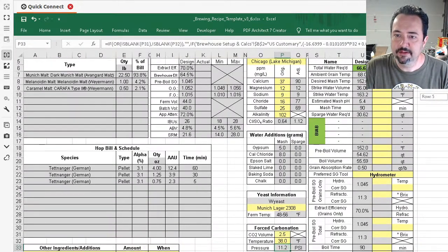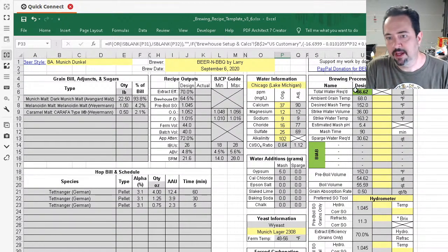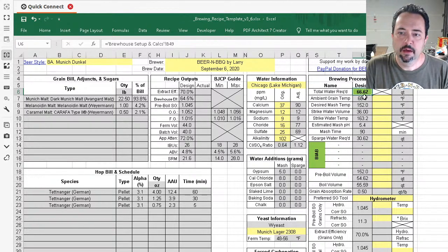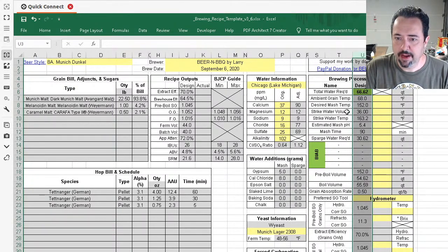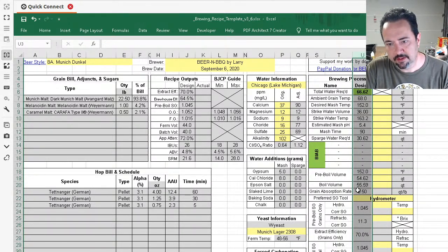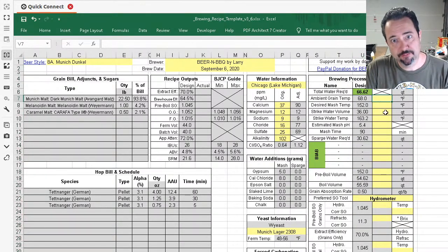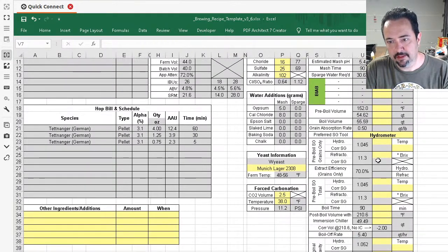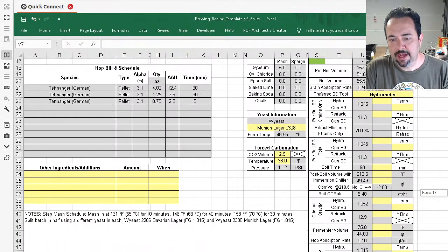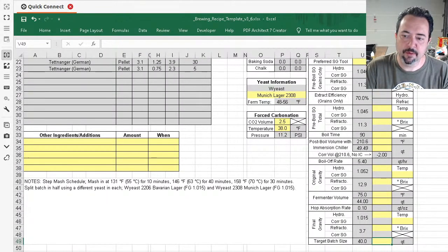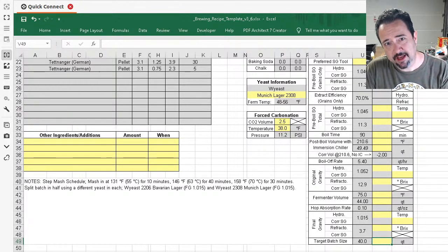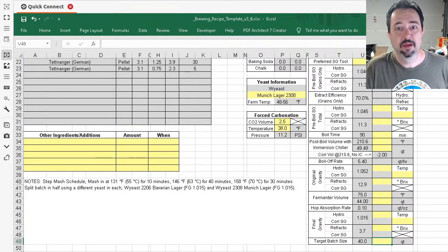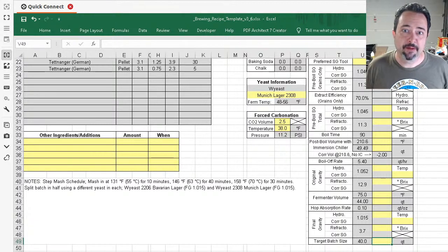And the whole right side is just a whole column full of operations that you start from the top, where you get the total amount of water required. In column U, you go all the way down, and it gives you all the parameters from water additions to temperatures to expected gravities. And on column V is where you enter in your actual measured values throughout the day. And by doing that, like I said earlier, you'll get some calculations done for you, all the way down to the keg, actually, down to your target batch size, which in my definition in this spreadsheet, batch size is how much finished beer you have in your bottles and kegs. Because why would you care about any other value? You want to know how much water and grain it will take to get 5 gallons of beer, not 4.5, not 4 gallons of beer. I want 5 gallons of beer in my 5-gallon keg.